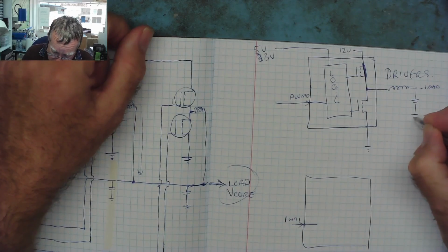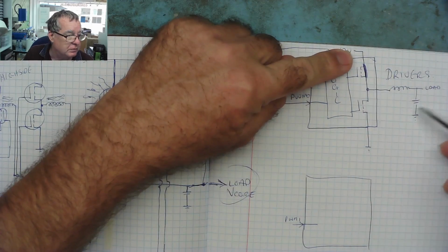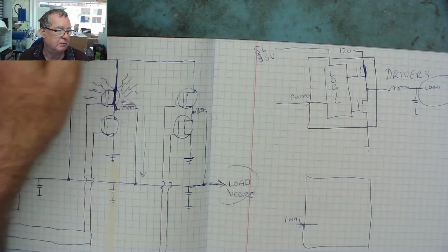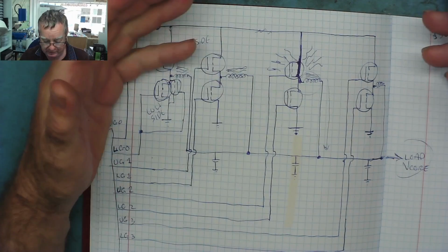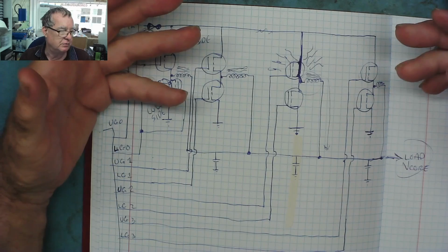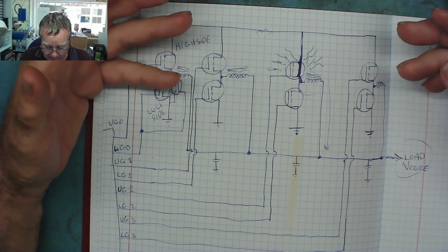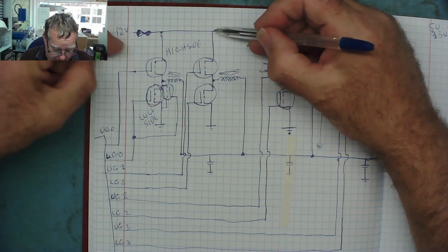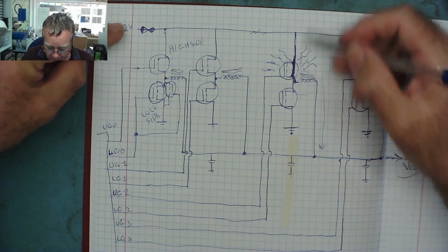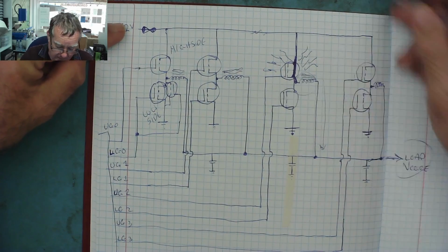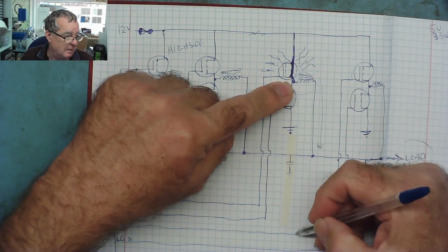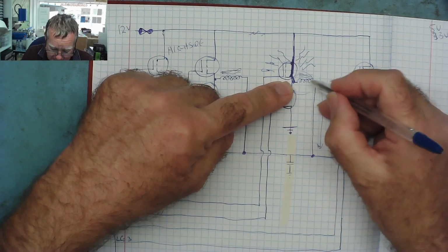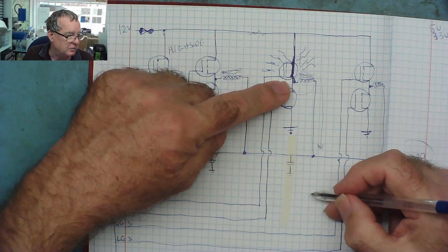Capacitors. And the same thing applies when you measure from 12 volts. You will see the resistance of the load. And this is where the problem starts: diagnosing faults in these circuits. Which MOSFET is short? And the reason it's a problem is this. You're measuring from the 12 volts to ground. The current's going down through one of these. If you then measure the resistance from here to ground, you'll actually measure the resistance of the load, as I've just explained to you.